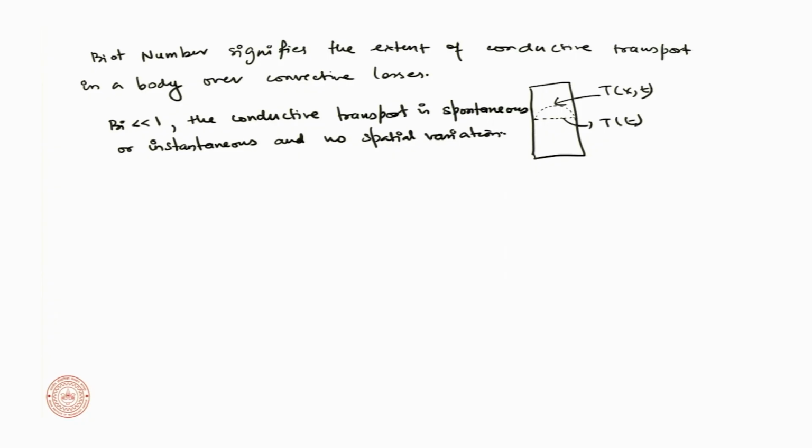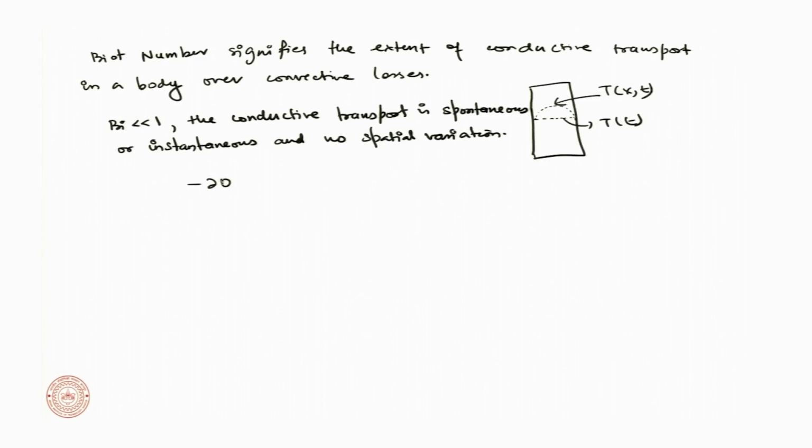Okay, what this means is, from a physical understanding, a body is conductive, it is able to dissipate heat very quickly and the temperature is flat. That's a physical understanding. Mathematically, how do we get it? Again, if you look at del theta bar by del x bar equals Biot number into theta bar. Ignore for now the dot n and everything at a given surface.